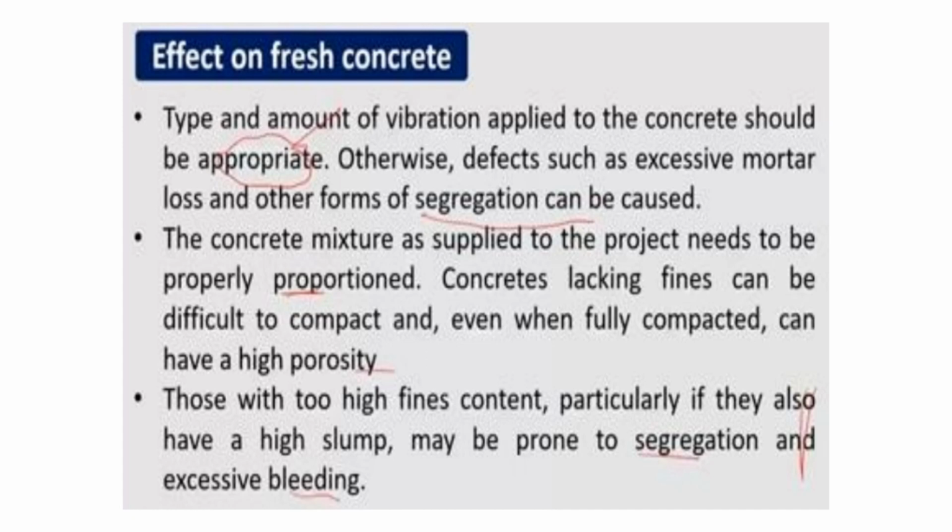The concrete mixture as supplied to the project needs to be properly proportioned. Concretes lacking fines can be difficult to compact, and even when fully compacted can have a high porosity. Those with too high fines, particularly if they also have a high slump, may be prone to segregation and excessive bleeding.